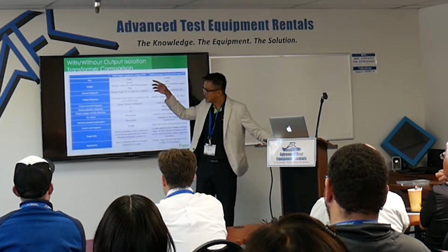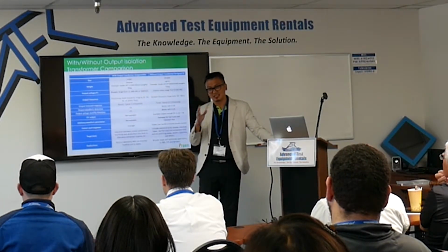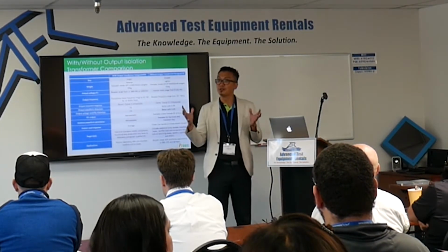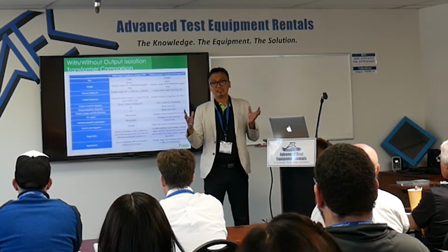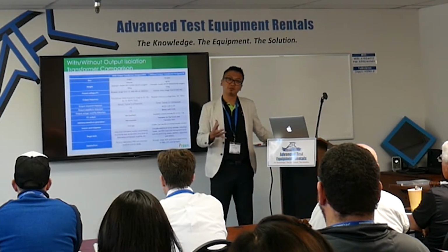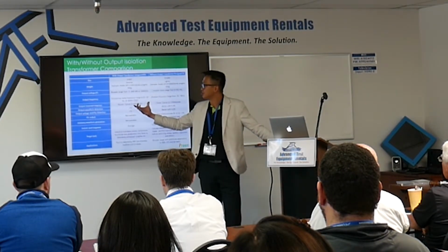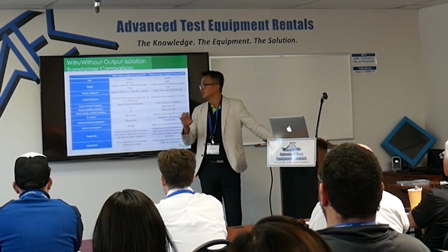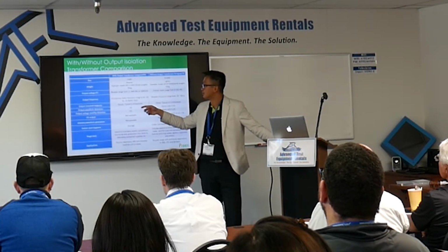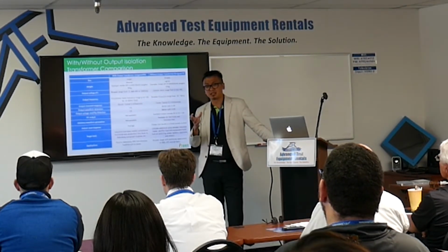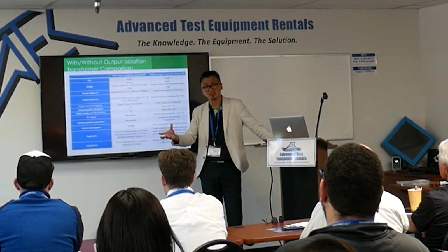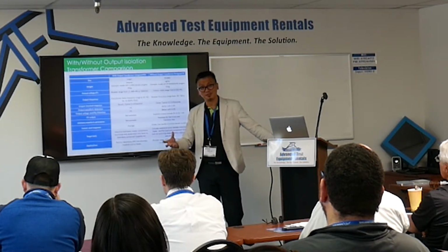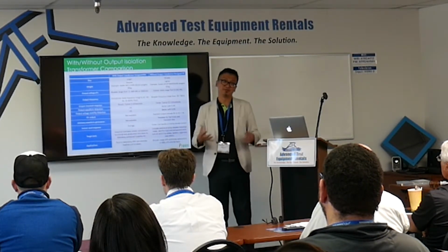Okay, but the isolation transformer, there are also disadvantages of that. Because isolation transformer manufacturer cannot make a wide range transformer. Nobody can make like a 1,000 hertz. So it's really difficult. With isolation transformer, usually you have a certain range only, because they saturate the transformer. So usually for the isolation transformer, you have to select a different range, like 45 to 65 hertz, or like 45 to 500 hertz.